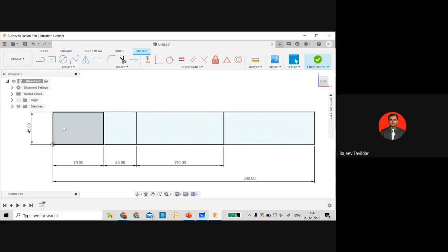The next step: this is the rise stroke and this is the return stroke, which we need to divide into an equal number of parts. As I discussed yesterday, the equal number of parts can range from 4, 6, 8, 10, and so on. Of course, not only even numbers, you can also use odd numbers, but as per standard practice, we are taking 6 divisions here.